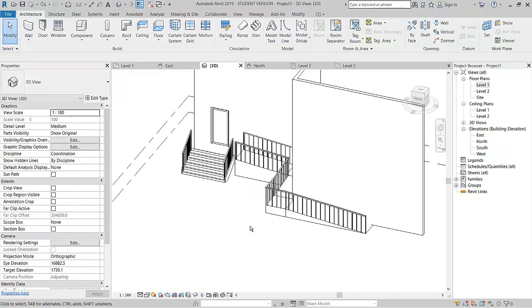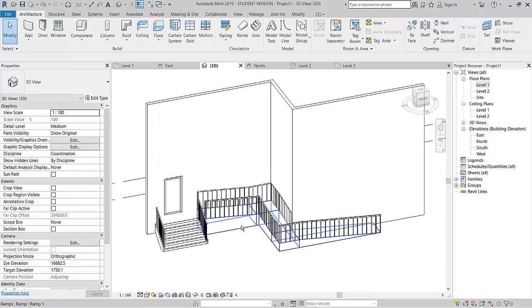Okay. So the idea here is if we don't have space to have all the length in one flight, we can move and rotate until we reach the distance. And remember again, if we have here 1 meter, so we need to move at least 10 meters. So normally the ramp is much longer than the stairs, so we need to calculate the distance or the length of the ramp carefully. And we will do this in our project, inshallah.